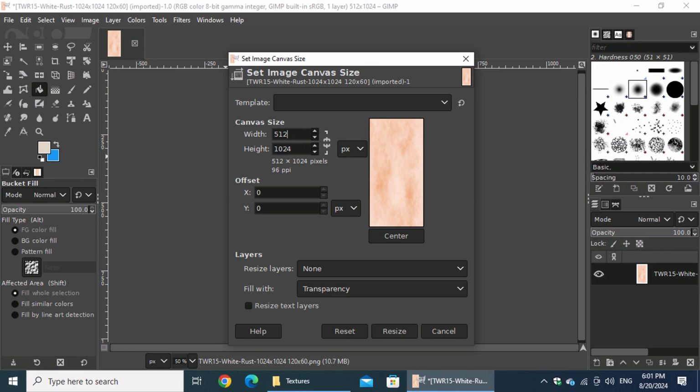For those who prefer a step-by-step breakdown, here's how the calculation works. First, we'll convert the units of measurement to millimeters. Next, we'll apply the formula 135.45 plus, open parenthesis, 135.45, which is the width of our image in pixels, divided by 600, which is the real width of the tile in millimeters, close parenthesis, times 3. This accounts for the 3 mm grout line.